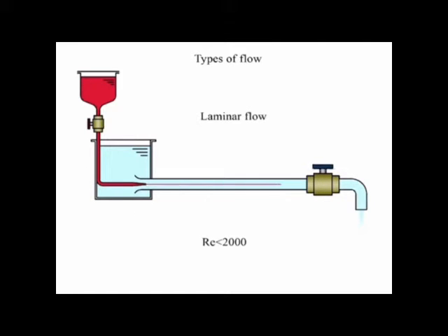If the velocity of flow is increased to a critical velocity, the type of flow changes from laminar flow to turbulent. When you open the valve more, the flow through the pipe will increase. The flow becomes whirling, the flow resistance increases, and thus the hydraulic losses increase. This is the turbulent flow. Turbulent flow is not usually desirable because the flow resistance and the hydraulic losses increase.